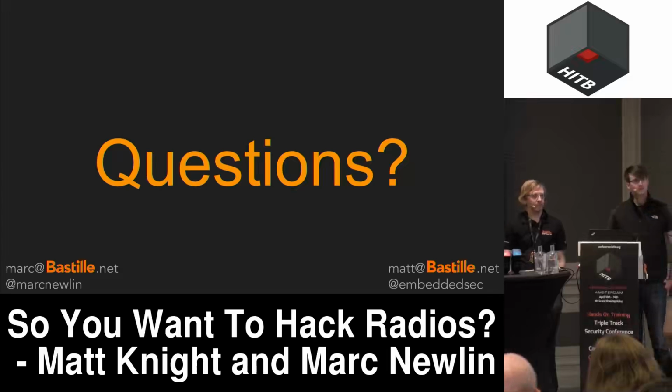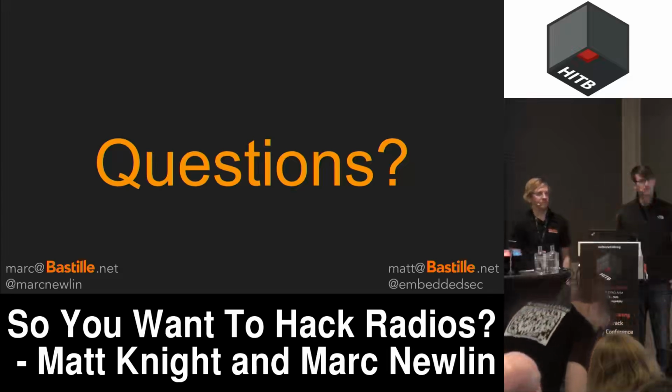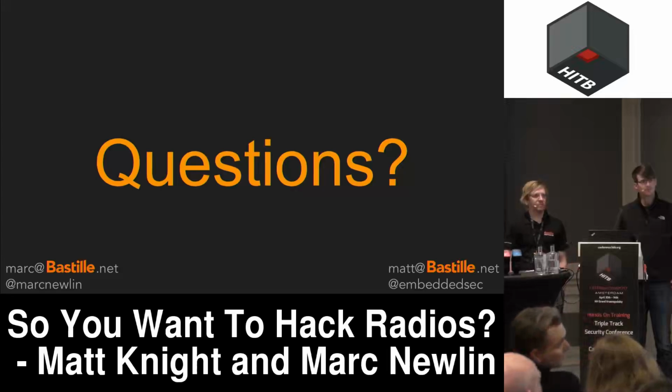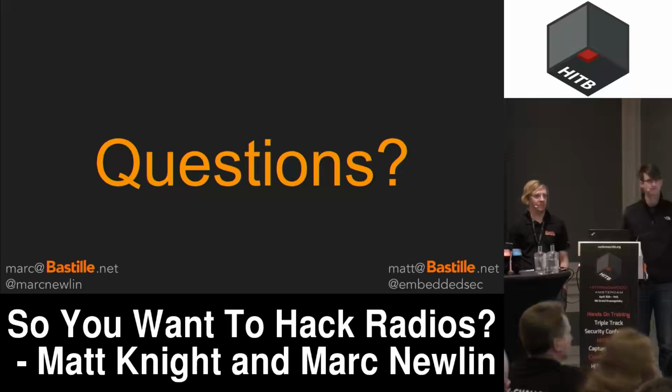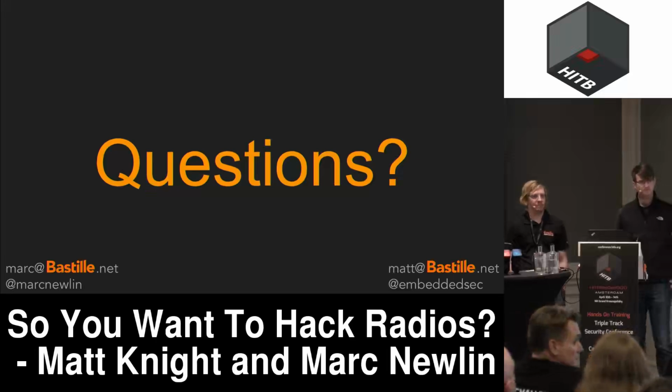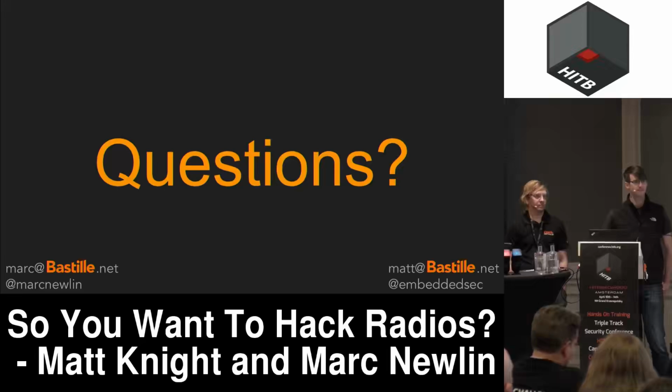Thank you for your talk. One moment in your methodology that might not be clear to everybody. Between the modulation or demodulation and the actual bytes, normally there also is an encoding or decoding. So how do you find that in a wireless protocol? When you have a wired protocol, it's sort of okay. We know that there's like Manchester encoding. We know like low level of signal is 0 and high 1, or vice versa. How do you do that in wireless?